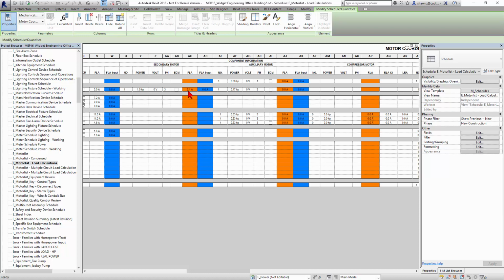Now in one of our previous videos, we were talking about how to go through and override some of the values with our auto-sizing components. You can actually override those and have it do some of the additional calculations for you. In this case, I have access to those exact same properties. I can see what's calculated, and I can see the input property, and if it's appropriate, and I go, you know what, 2.1 amps is not what I want, 2.5, and so I can enter that as the value. That'll become the new value that gets reported to the actual real schedule over here in the motor list. But I have control here to put in whatever overrides I feel are appropriate when I'm working with this.